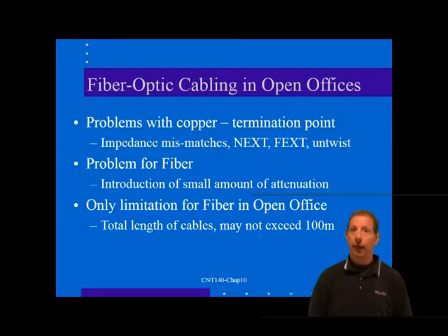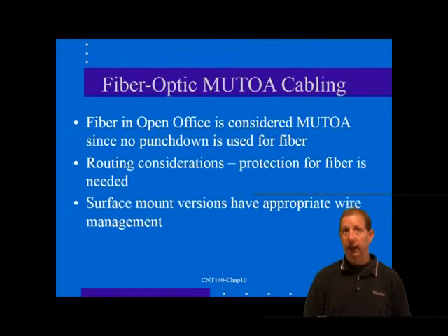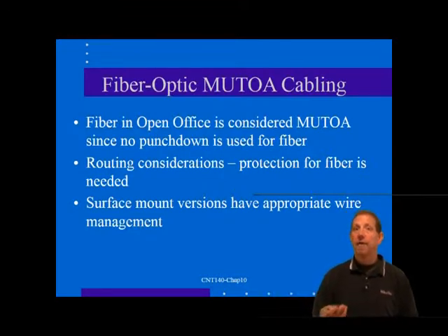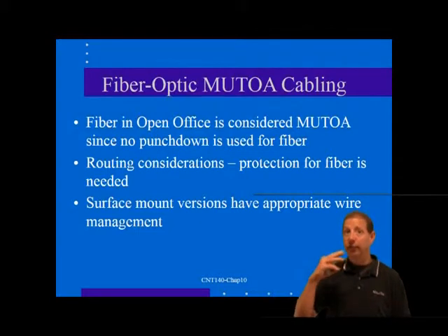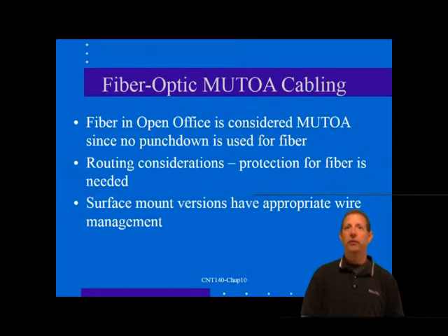Now, using fiber optic MUTOA cabling for open office is always considered to be the multi-user outlet method. Fiber cabling does not use the punch-down method for copper wire and thus cannot use the consolidation point method. However, there are several important considerations for using fiber with open offices.